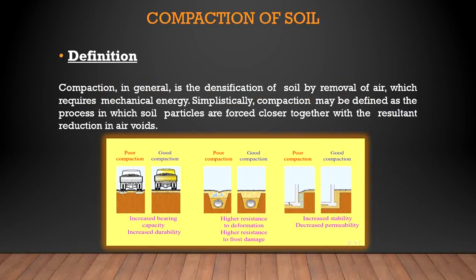In its natural location and condition, the soil provides the foundation support for many structures. Besides this, soil is also extensively used as a basic material of construction for earth structures such as dams and embankments for highways and airfields. The general availability and relatively low cost are the chief causes for using soil as a construction material. When properly placed and compacted, the resulting soil mass has better strength than many natural soil formations, and such soil is referred to as a compacted earth fill or a structural earth fill.